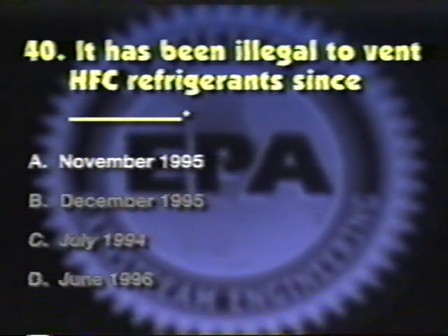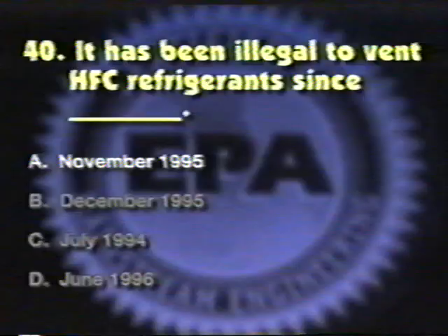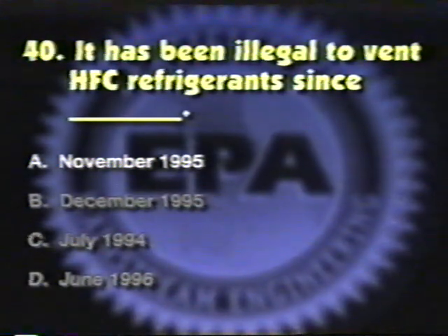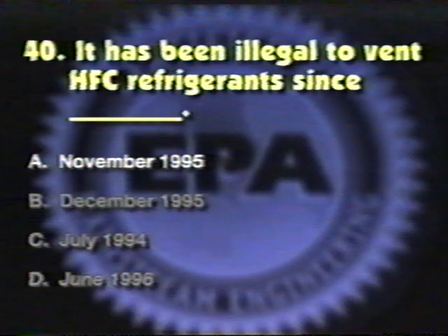The correct answer is A. Since November 15, 1995, HFCs and other refrigerants with a zero ozone depletion potential are also subject to the restriction on venting because they are greenhouse gases, meaning they contribute to the global warming problem and must be recovered.